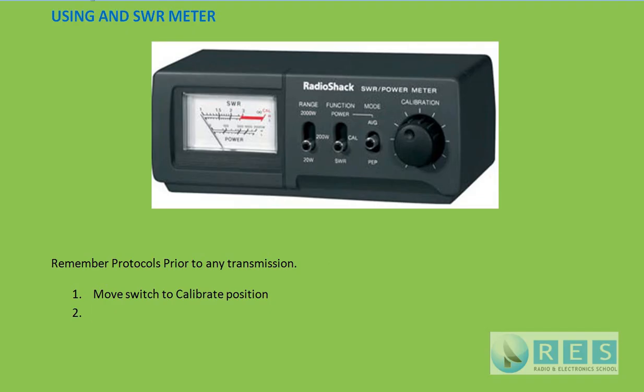We've already announced our call sign, so we're going to transmit the carrier, and we're going to do that on AM, that's double sideband, not single sideband. We could do it on CW, Morse code, or we can do it on FM, because that would give us a carrier. And three, we're going to adjust the calibrate knob here. So we're transmitting. This switch is on calibrate, and we adjust the calibrate knob so the SWR meter needle comes all the way over to calibrate.